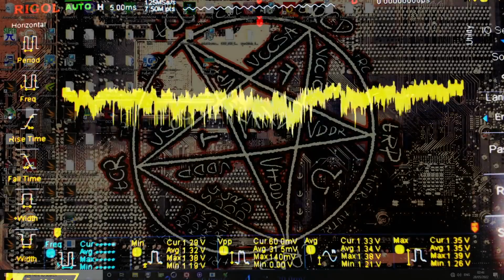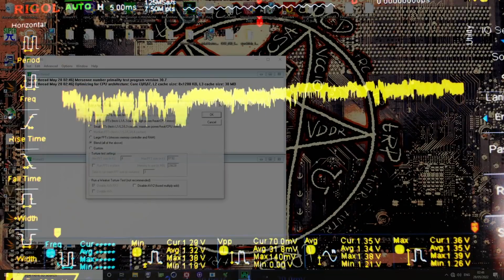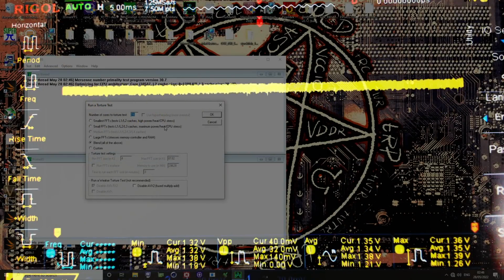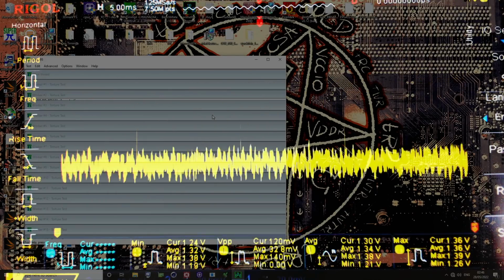Kind of makes me wonder who has the... So I've already tested the Apex, but I've just not done it on video, and I don't think I took any notes. The other issue is, again, the board impedance is just, you can't compare motherboards based on measurements from the back of the socket, which really, really annoys me. Anyway, here goes small FFTs.